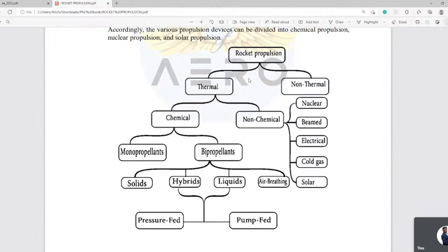And second, you might have seen that we previously had a conical nozzle, now we have a bell nozzle, gradually converted into a dual bell nozzle. What is the reason behind it? Because that shape provides a huge number of expansion waves. What is the property of an expansion wave? Behind the flow, it decreases the static pressure and helps to increase the velocity or the Mach number.